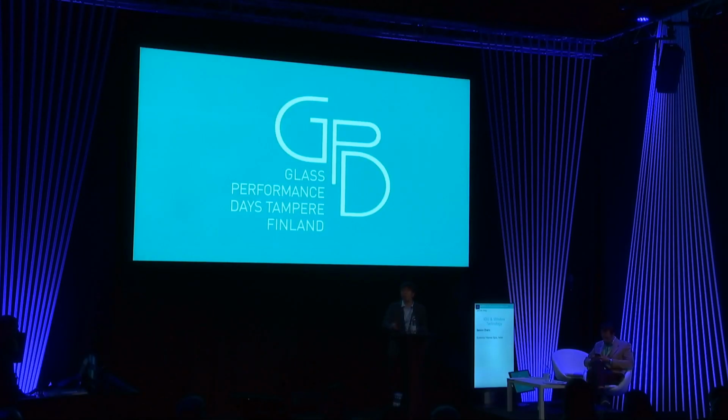For the advantages of VIG, as I just showed on the slide, it has much better thermal insulation and sound reduction than the normal IG unit, because there is no air inside. Basically, it's a vacuum, so it can keep the heat in and also isolate the sound. For these two advantages, no IG can compare with VIG. So we truly believe VIG can be the future of the market. Thank you.